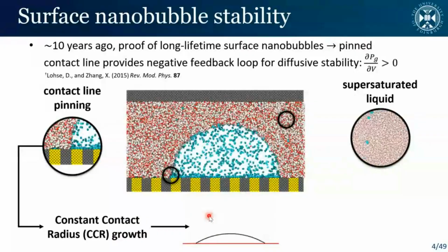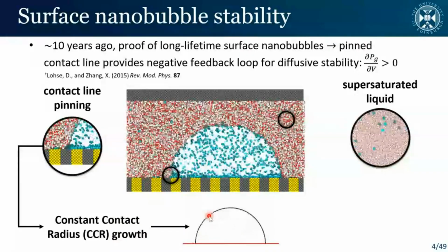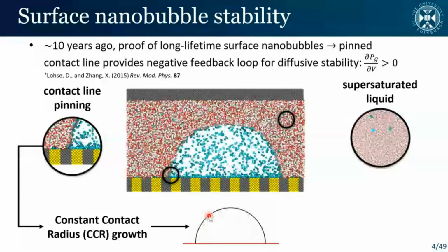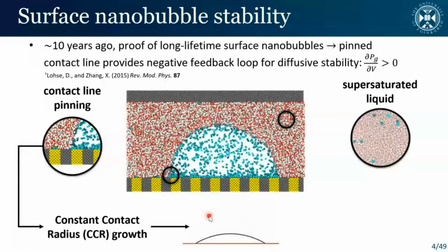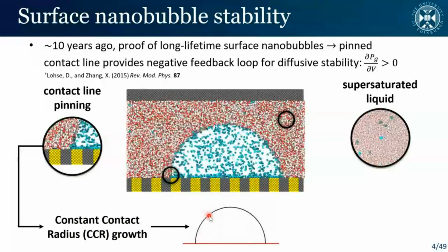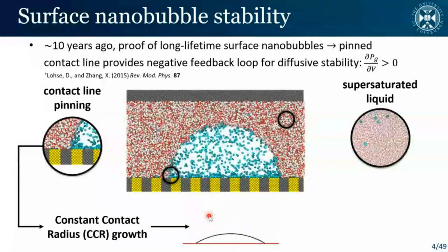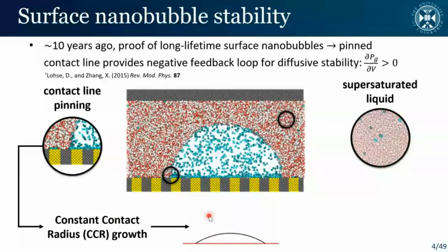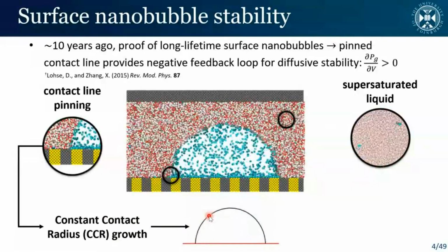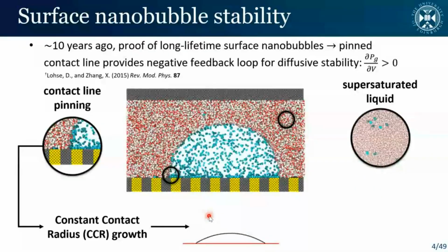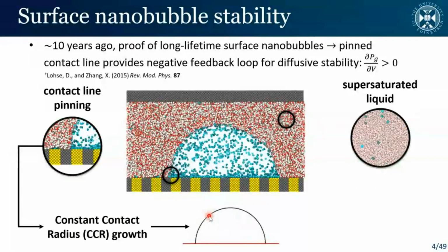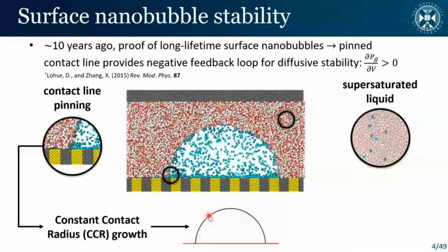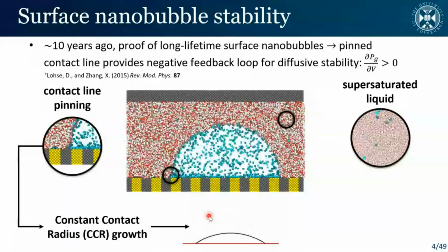Yes, so I should make clear this is all run in LAMMPS. We have, as a group, implemented some custom potentials for the water models. That is to get by without using long range solvers in all the simulations. I'm now using long range solvers, but previously for efficiency we were using a slightly more efficient solver which didn't need these long range corrections. If that means anything to people who use molecular dynamics.